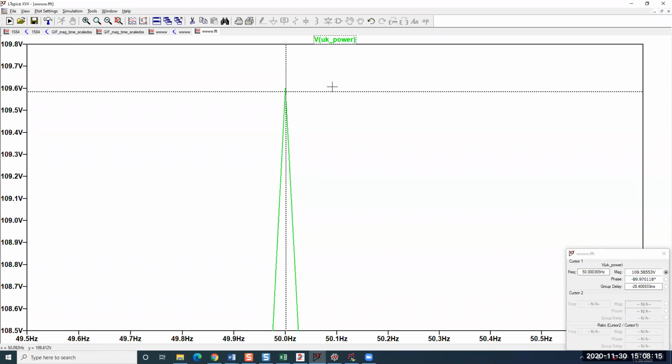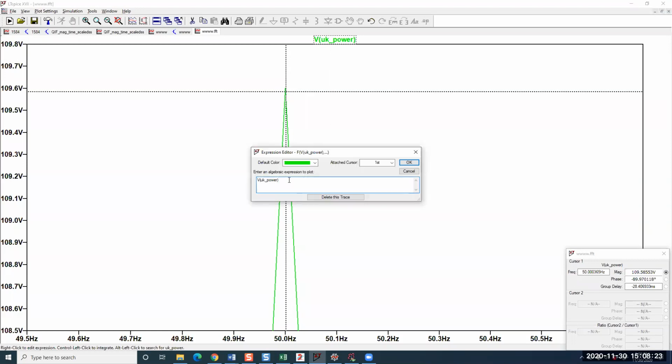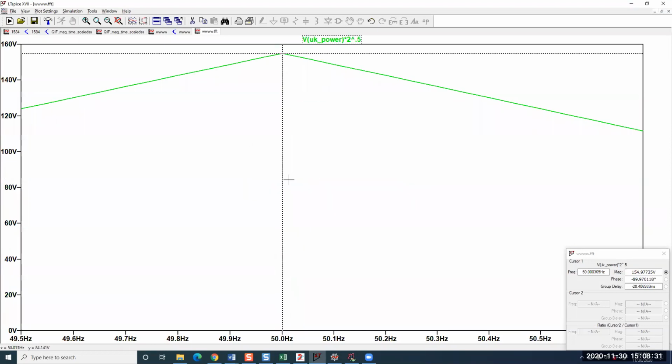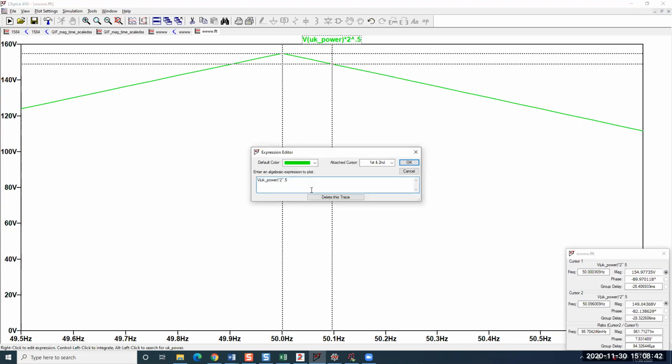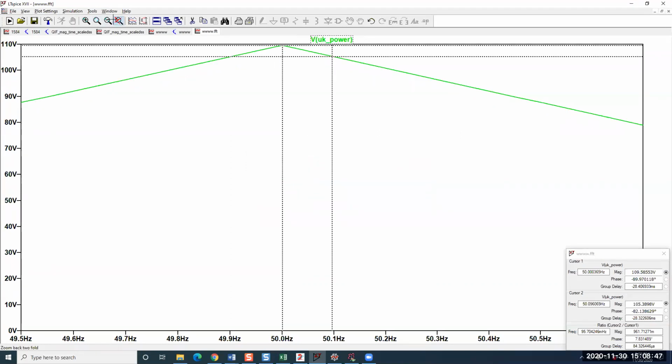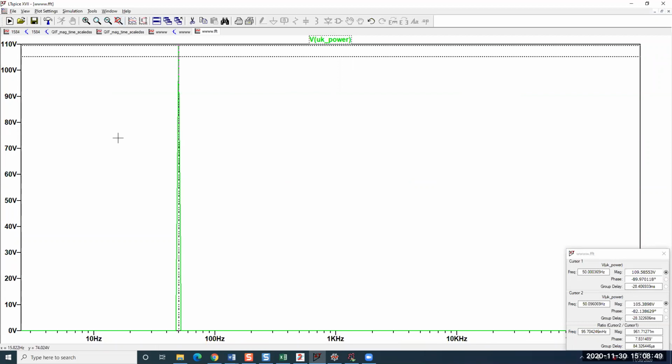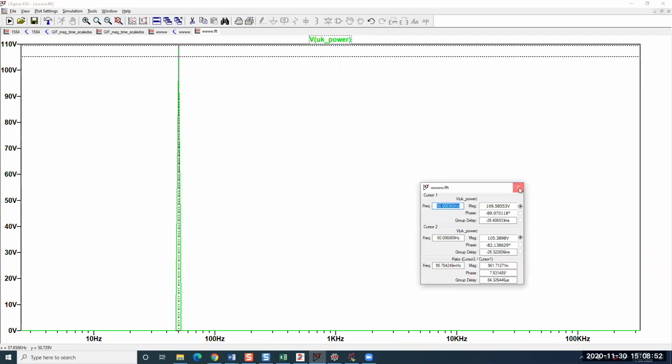Right, because the FFT naturally gives us the RMS value peaks, where in Scopy you can show the RMS or the amplitude. So if I want the actual amplitude, I just convert it, right? And now we're back to 155. So that would be the amplitude. But it's a clear case of seeing that the FFT in LTspice does RMS. It's not exactly told to you in an easy way.